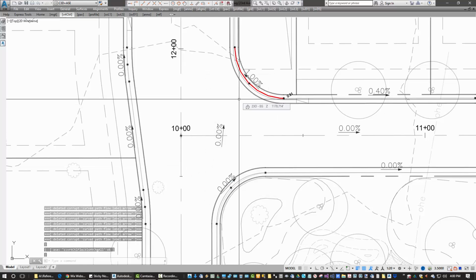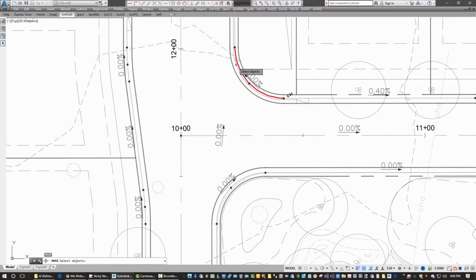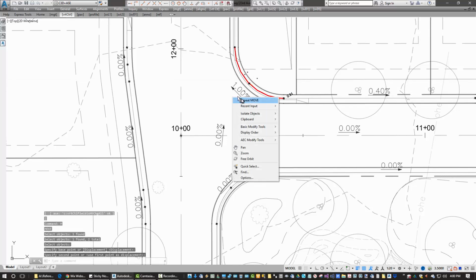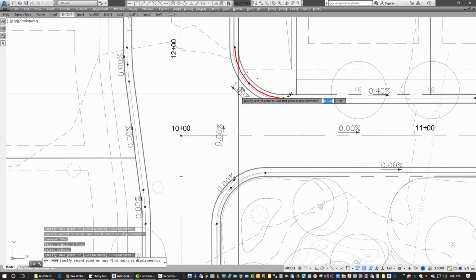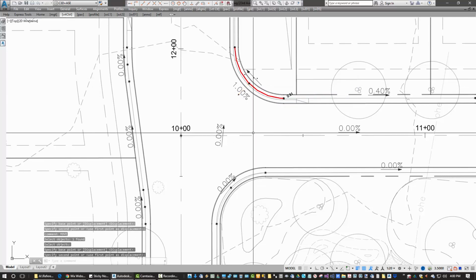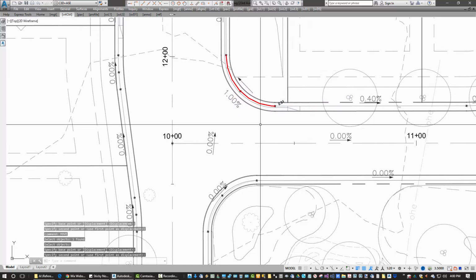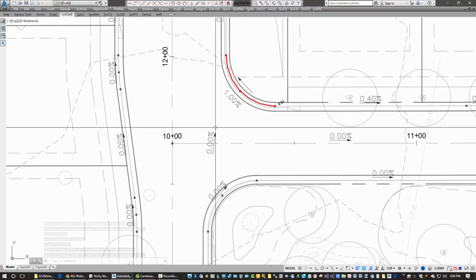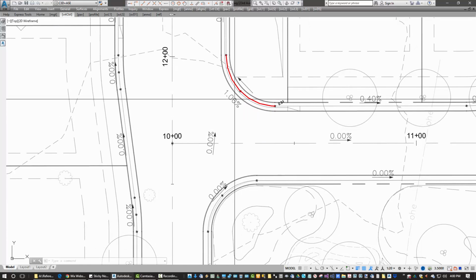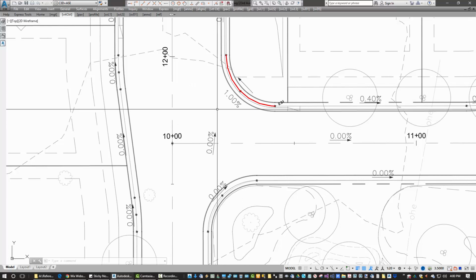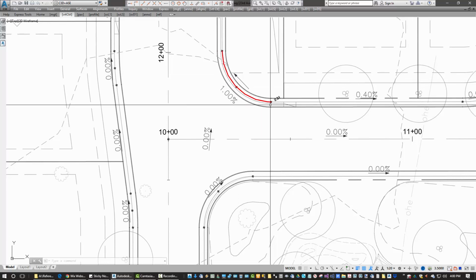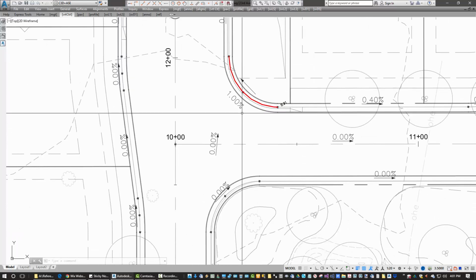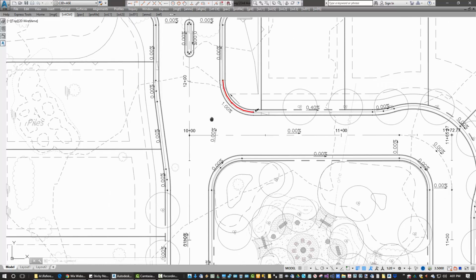Another thing about flow labels is that you can move those anywhere you want in the drawing. They're not special. They reference the data that ASE is managing, but it doesn't do anything to it. So you could erase the flow label, it would have no effect. And you can move each of the components independently. So we've established a 1% grade from this marker to that marker. So when these elevations start changing, that 1% will stay there. And that's how you create a constraint.